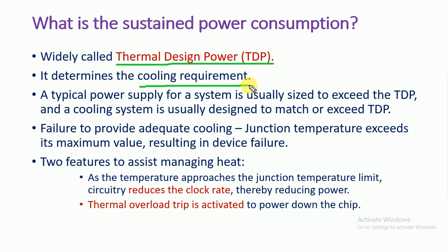If it receives power from the power supply, and if it is consuming more power than is required, there should be some provision, because automatically that additional power will generate some heat. So heat will be dissipated, and we need to avoid that heat. For that purpose, we are using a different mechanism based on the thermal design power. So thermal design power is a cutoff from where we need to have some additional feature added.